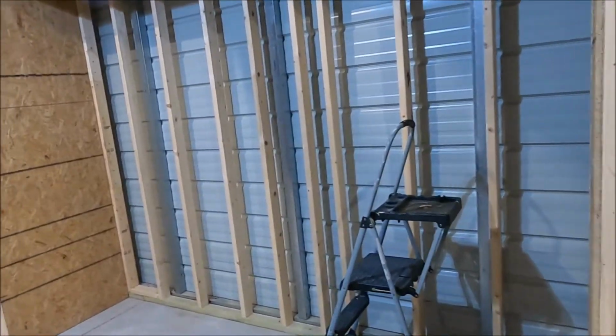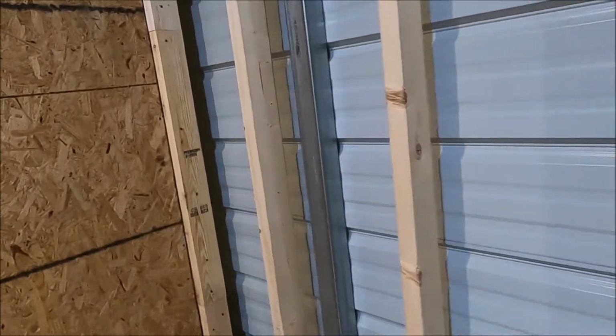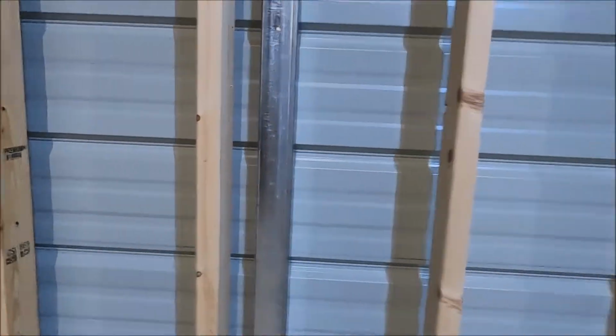In this little area where I'm gonna have my tool bench, I'm gonna have a Ryobi charger here, and I'm just gonna put a few outlets along here, because the most I'm gonna do with this is maybe put in a small drill press, maybe a little bench grinder, and a few things here and there, but I won't be using them all at the same time. And so I know I won't go over the 16 amps of the 20 amp circuit. So I'm gonna put 3 outlets in here, and I'll be totally fine.